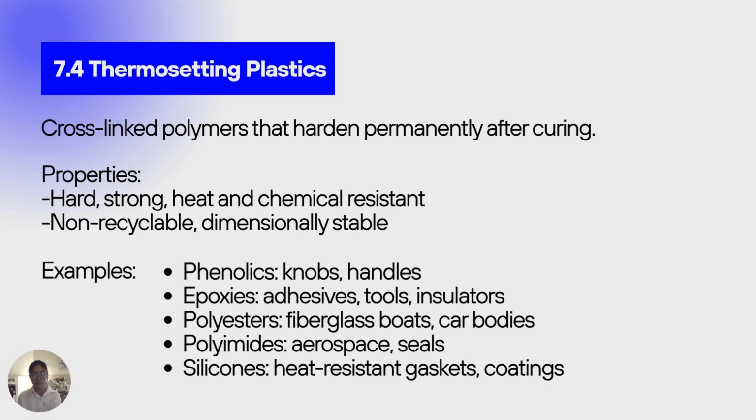This irreversible reaction is what gives thermosets their high-strength dimensional stability and resistance to heat and chemicals. Examples of common thermosets include epoxies, unsaturated polyesters, and silicone. These materials are typically formed by compression molding, transfer molding, or reaction injection molding, followed by curing through heat or a catalyst.